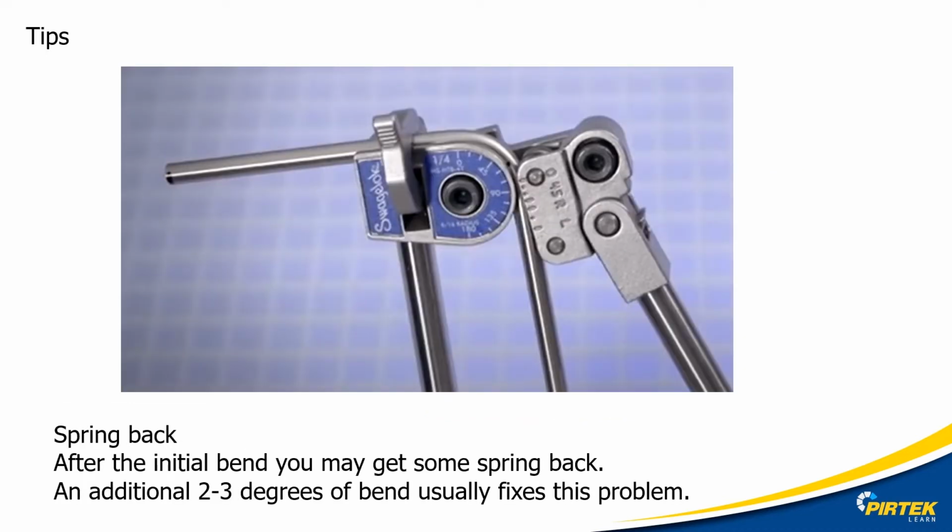There may be a bit of spring back. If this does occur, add another 2 or 3 degrees of the bend until that fixes the problem. Again, this will vary from material to material, but you'll eventually get the feel for it.